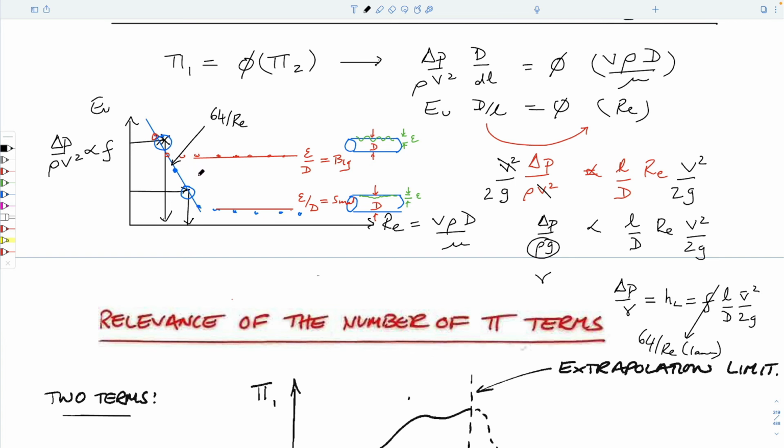When we talked about the Navier-Stokes equations, we converted them into the equation for flow within a parallel-sided duct and also flow within a tube. And we ended up with some relationships. Importantly, those relationships were only for this regime, the laminar regime. And so the equations that we developed, which were basically this expression here, were only for the laminar regime.